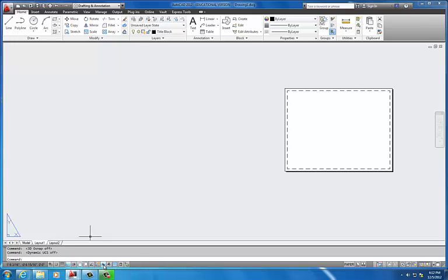I don't need this. I don't need this. I think I'll leave my dynamic input just for your reference. You can see what I'm typing a little more clearly. But it's up to you if you want to use it or not. So in this case, I'll use ortho, object snap, and dynamic input. Okay. So line tool, specify first line.